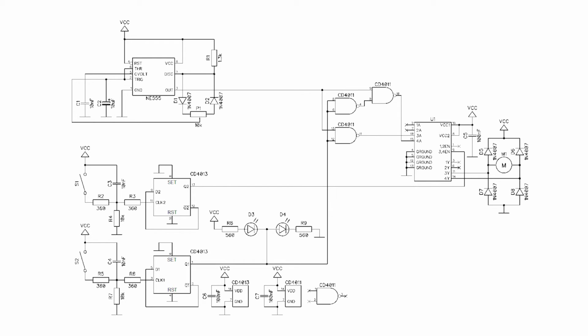In addition, we note that the diagram has small blocks with 100 nanofarad capacitors. We have already mentioned the use of these elements. They are used here to filter the supply voltage. Their application is even more desirable because motors belong to the elements generating a lot of noise.